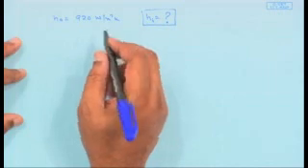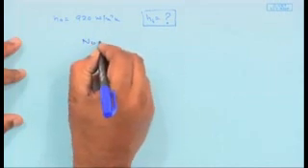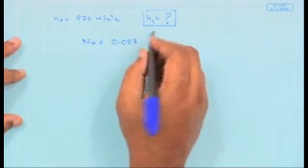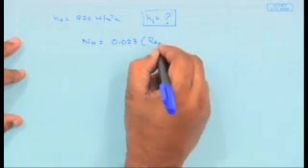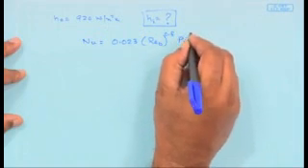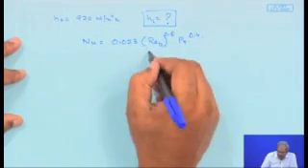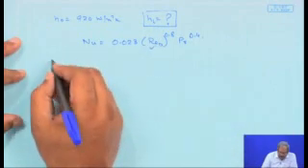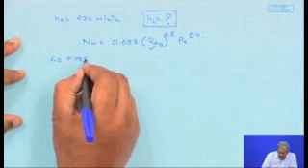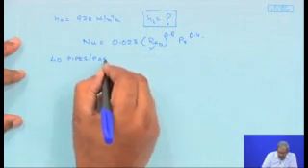In order to do that, I am going to use the relation which we have seen many times, the Dittus-Boelter equation, Reynolds number based on diameter to the power 0.8 and Prandtl number to the power 0.4. So, in order to calculate Reynolds number, I understand that I have 40 pipes per pass.